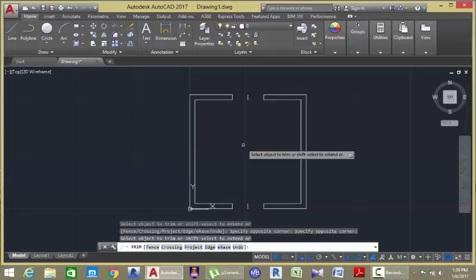You have two options which start with the letter E, the edge option and the erase option. For the edge option, I've already used E for the alias. That's why AutoCAD ignores the first letter in erase, which is the E, and uses the R, the second letter, as the option for erase. Now type R on your keyboard and press enter. AutoCAD brings you into erase mode.